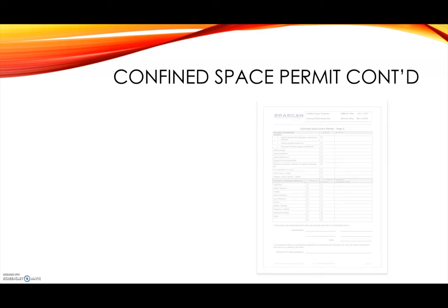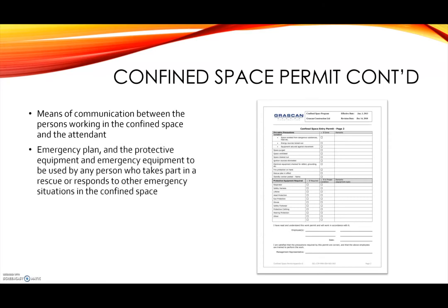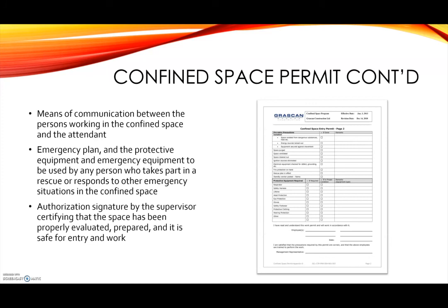Confined space permit continued. Means of communication between the persons working in the confined space and the attendant, emergency plan and the protective equipment and emergency equipment to be used by any person who takes part in a rescue or responds to other emergency situations in the confined space. Authorization signature by the supervisor certifying that the space has been properly evaluated, prepared, and is safe for entry and work.